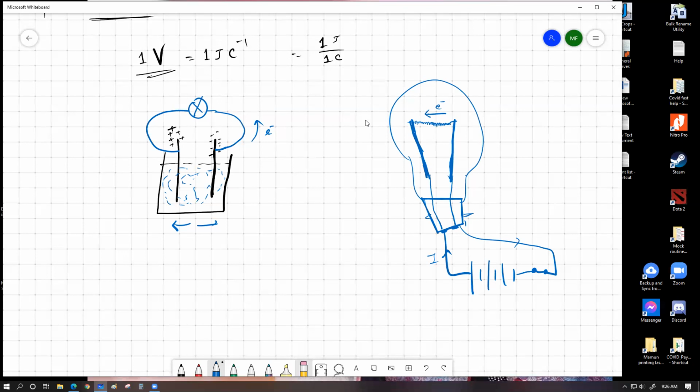Whenever electrons flow through this part, they are going to spend their electrical energy within this wire, and that will heat up this filament coil, and it will heat up and heat up and heat up. As the object starts to heat up, it produces a lot of heat, and it will also slowly start to change color from red to orange to even a very bright white color, depending upon the temperature. So that's basically how a filament lamp works, by primarily heating the filament. Now, in this process of heating the lamp, consider the amount of energy that each of the electrons has when it enters the filament lamp right over here.